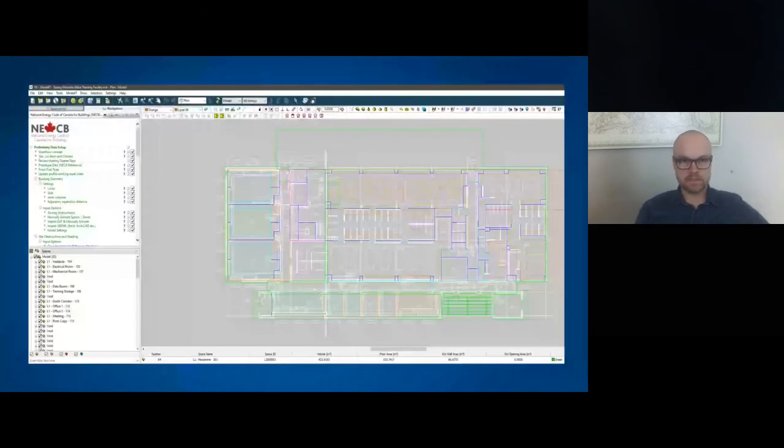So this is just a snapshot of the software. This is IES. IES is kind of an amalgamation of different modules. I've got three that we use the most. This is the modeling portion. This is where you put in all your different spaces, and then you define each space as far as the materials that go into your walls and your roofs.